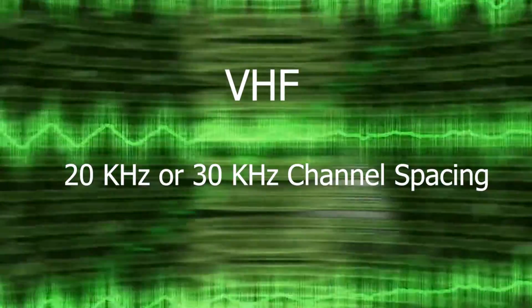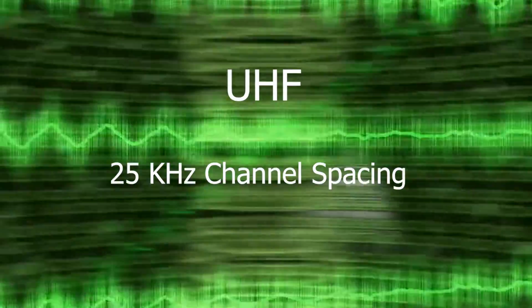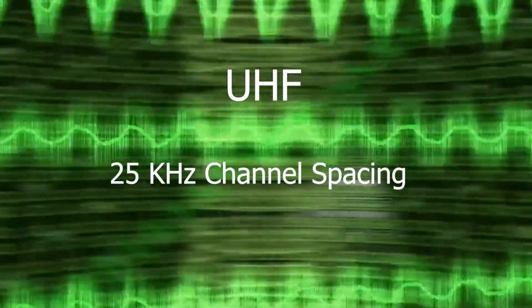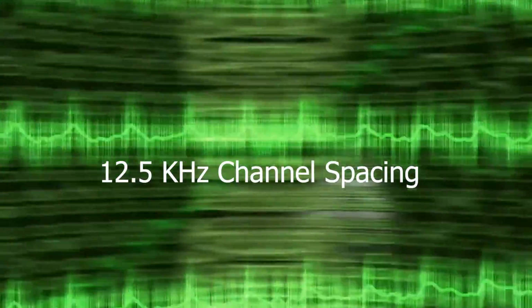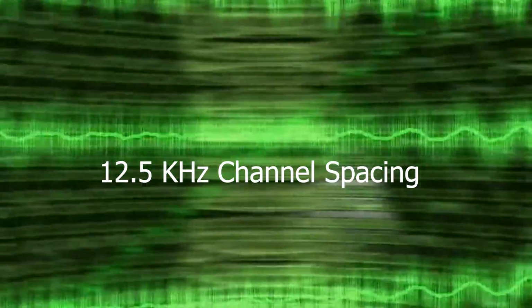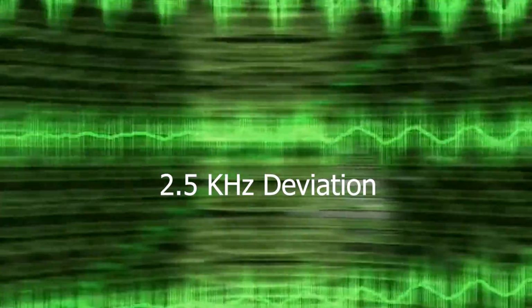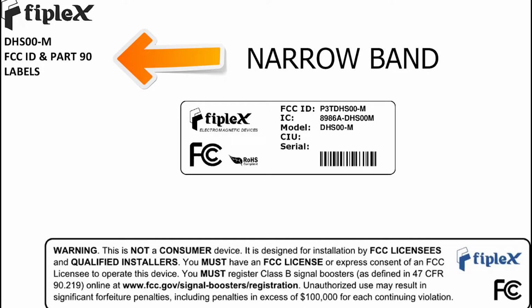Wideband is typically 20 or 30 kilohertz channel spacing at VHF, and 25 kc channel spacing at UHF. Deviation is 5 kilohertz. Narrowband is half of that, 12.5 kc spacing and 2.5 kilohertz maximum deviation. Everything you'll find in FCC Part 90, the commercial bands, business and public safety, is narrowband.